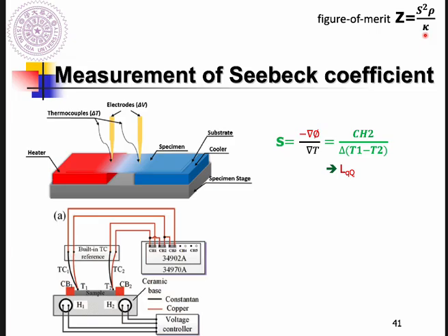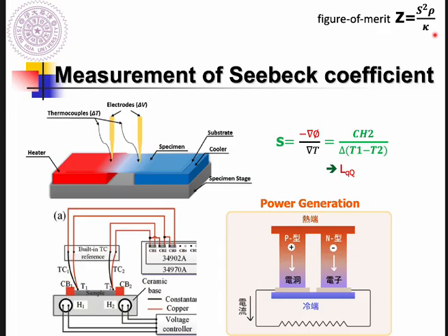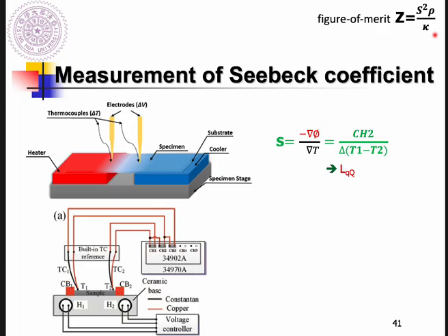Okay, so in most cases, semiconductors are usually suitable for thermoelectrical applications. Also not polymers, right? Polymers have poor electrical conductivity, even though they have a lower thermal conductivity. So it's some kind of balance. In most cases, people use semiconductors as the best thermoelectrical materials. And for real thermoelectric applications, people usually use P-type or N-type semiconductor materials.